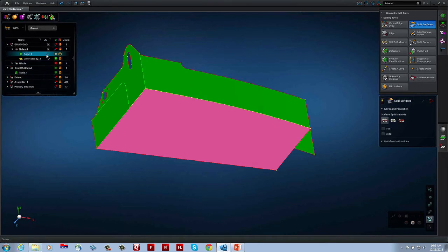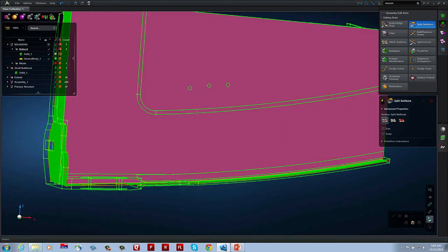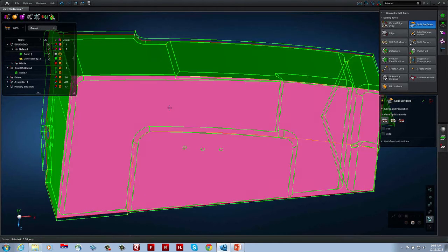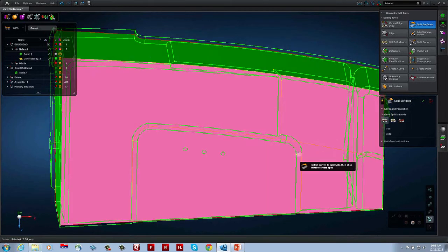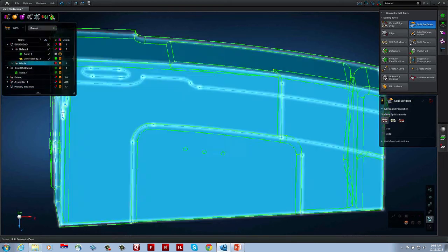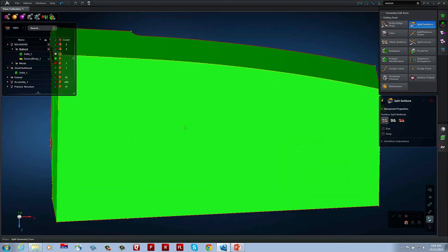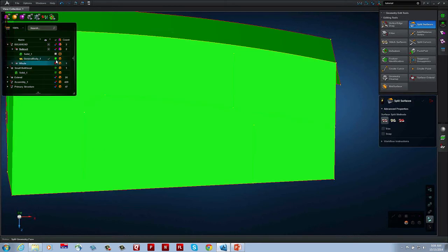So I'm going to split the web at this guy, this guy, this guy, and there'll be a couple on the front. I'll do this guy and this guy. Notice that I didn't select the little round part. I'm doing some idealization here, all right? So this edge here, when it splits, is not going to go all the way to that one, and that's not a big deal, because once I get the split in place, I can actually do a vertex drag.